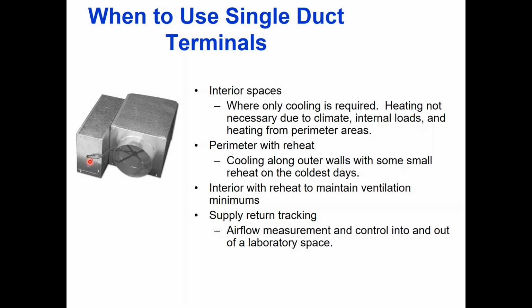But as soon as you start adding things like heaters or fans, now I'm going to have high voltage power as well as low voltage power, so now I'm going to need an enclosure. On these small single duct boxes without electric heat, I don't have any high voltage, so I don't need a control enclosure. However, if you're doing something in the city of Chicago proper, you're going to have the enclosure if it's a plenum return, because everything in a plenum has to be in conduit and hence in an enclosure.